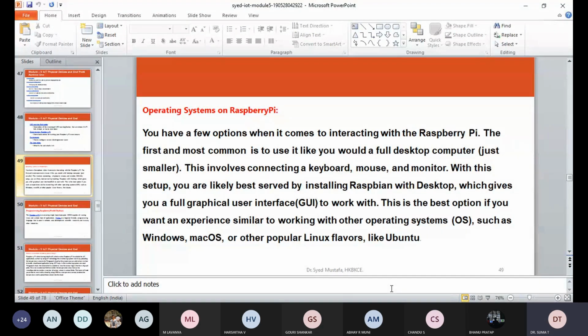We recommend using Raspbian: tick the box next to Raspbian and click on install. Raspbian will then run through all its installation process. Note that this can take some time. Okay. When the installation process has completed, the Raspberry Pi configuration menu, that is raspi-config, will load. Here we should set the time and date for our region.